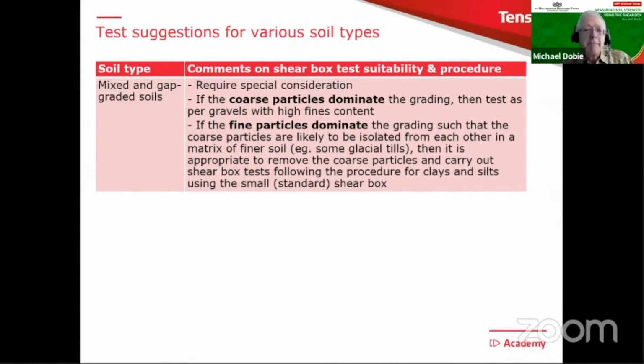Then the last soil, just to mention quickly, are what I'm calling mixed or gap graded soils. Now these may not be as difficult as you think. And there are two main approaches. So if you have a gap graded soil in which the coarse particles dominate the grading, so you're going to have coarse particle rubbing on coarse particle to give you shear resistance, then you could just test them as gravels with a high fines content, and maybe even consider going dry and removing some of the fine material. But you've got to be careful.